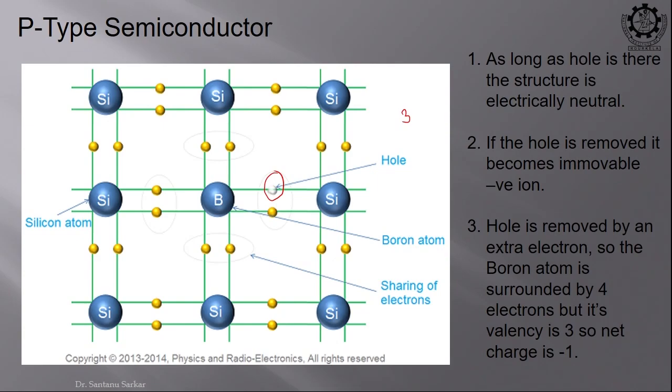So, each silicon shares with 4 adjacent atoms to achieve 8 electrons in the outermost orbit. When one silicon is replaced by a trivalent material, that is boron, that particular connection will have one mismatch, or one vacancy of the electron. That we term as the hole, so with trivalent doping, the majority carrier will be the hole, right.